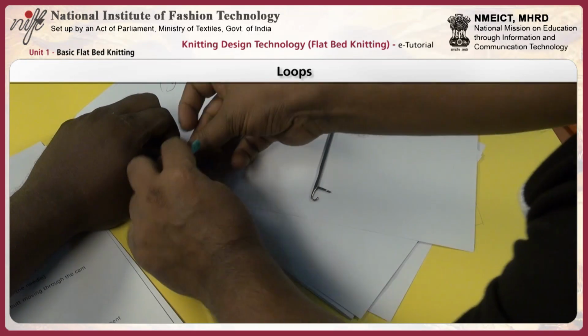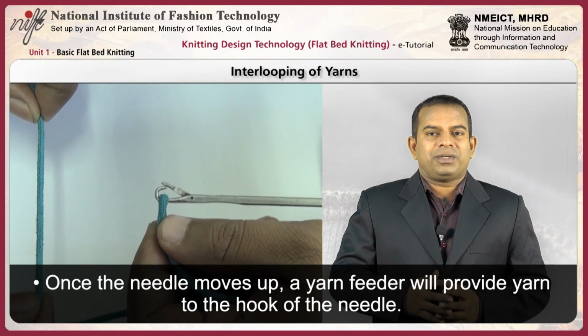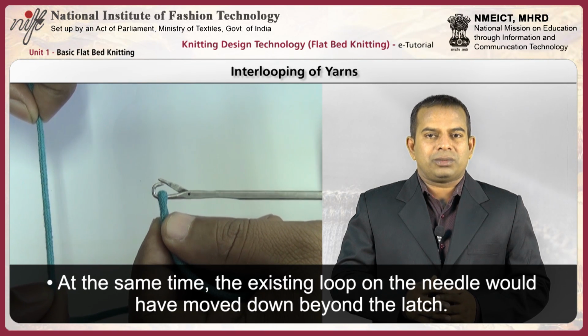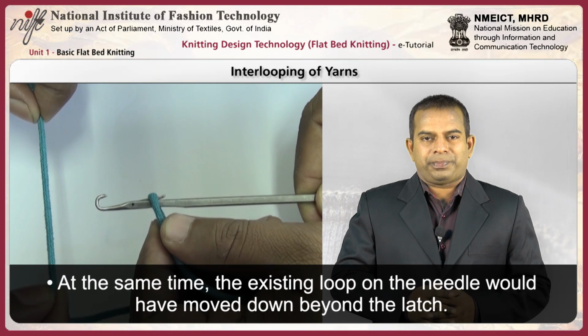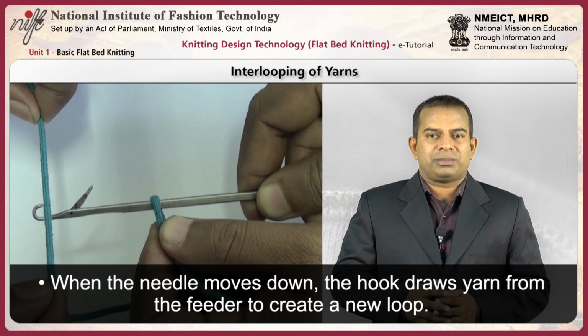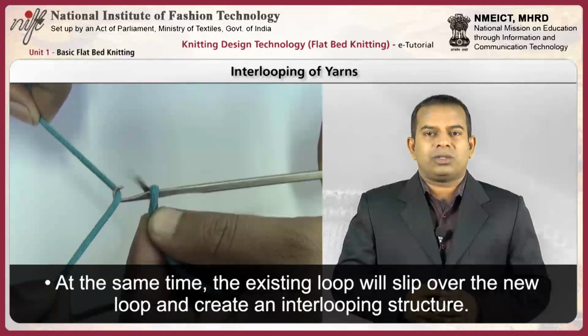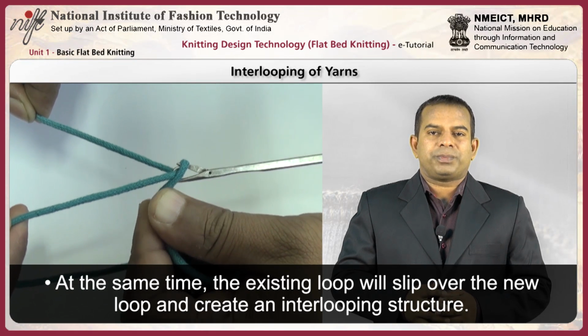I will show it once again. Once the needle moves up, a yarn feeder will provide yarn to the hook of the needle. At the same time, the existing loop on the needle would have moved down beyond the latch. When the needle moves down, the hook draws yarn from the feeder to create a new loop. At the same time, the existing loop will slip over the new loop and create an interlooping structure.